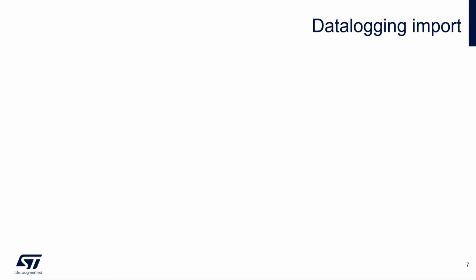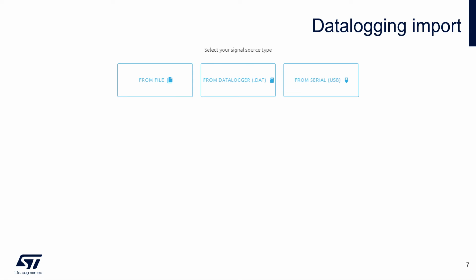To better understand the data format expected by the NanoEdge AI Studio, let's briefly review the possible ways of import. Each will be practically demonstrated in a specific chapter of this training. The NanoEdge Studio expects data in plain text, usually each signal separated by an ASCII code corresponding to a carriage return line feed, so a new line, and each sample separated by a delimiter that can be configured in the import window. The from serial option,